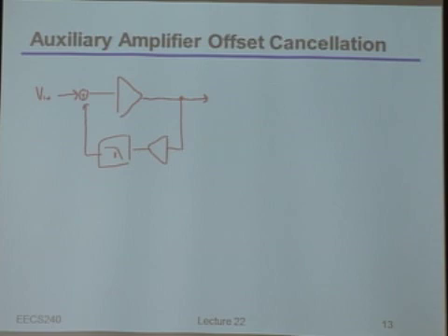Now, based upon the confused looks that I'm seeing, that's not to say that this only cancels the offset. So what else does it actually cancel if I do things this way? Yeah, it also cancels your signal. Now, which part of the signal does it cancel? Yeah, it cancels the low-frequency part of the signal.